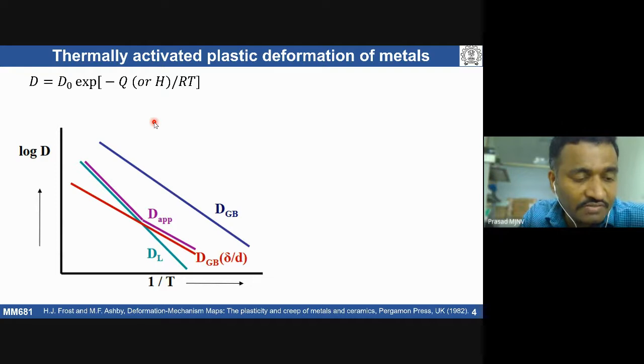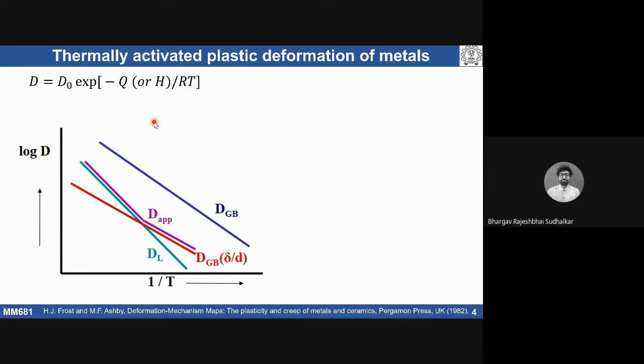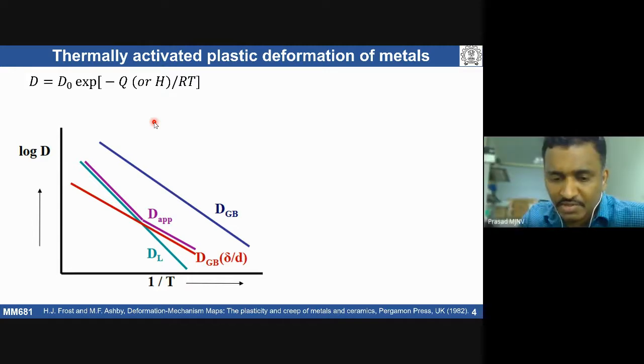You're right. What is the meaning of self-diffusion? The atoms in a material, after the application of thermal energy, diffuse within the material with the help of vacancies. If we take the same type of atoms, and an atom has to jump from one lattice position to another position, there will be an activation barrier.